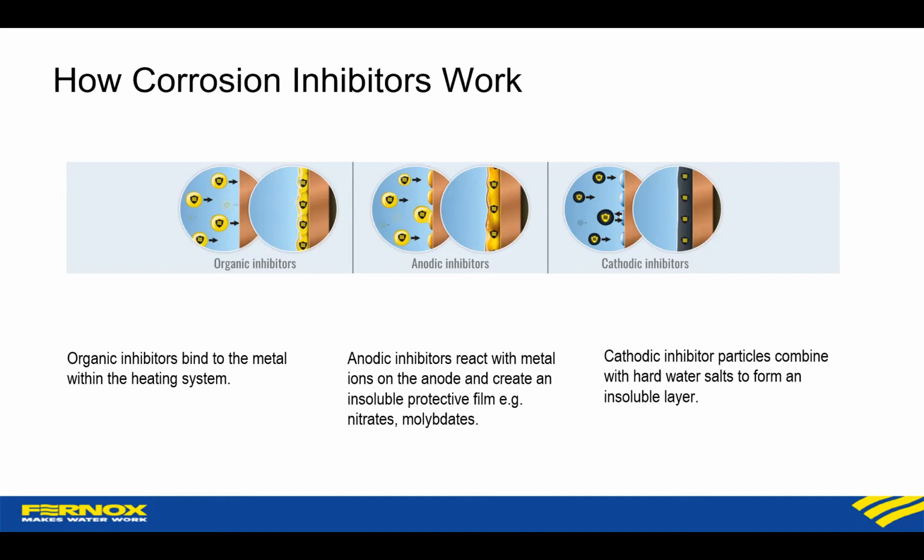Soft water can be particularly corrosive. It also gives you more pH buffering, so hard water is more likely to keep the pH in the range you want it, about 7 to 8, slightly alkaline. That tends to be the best for most metals.